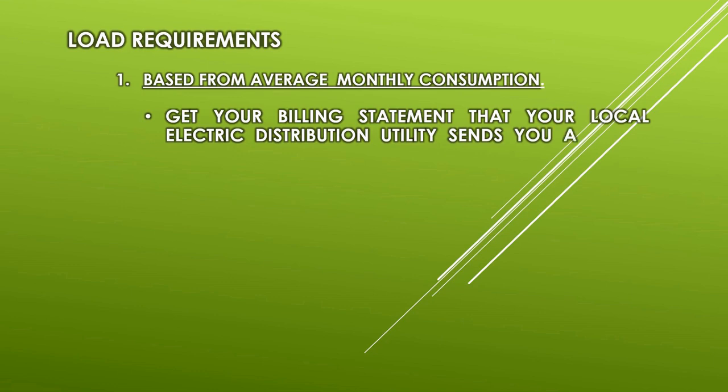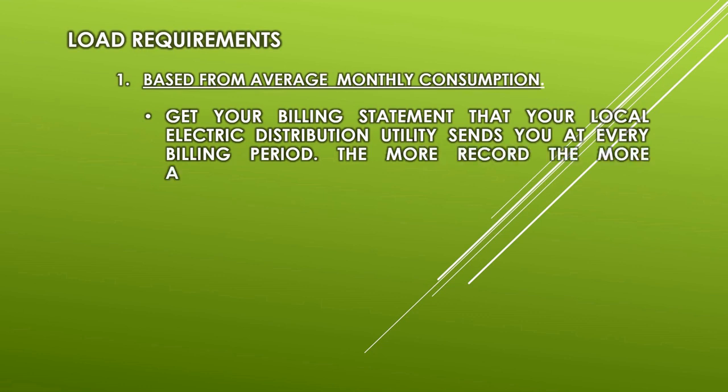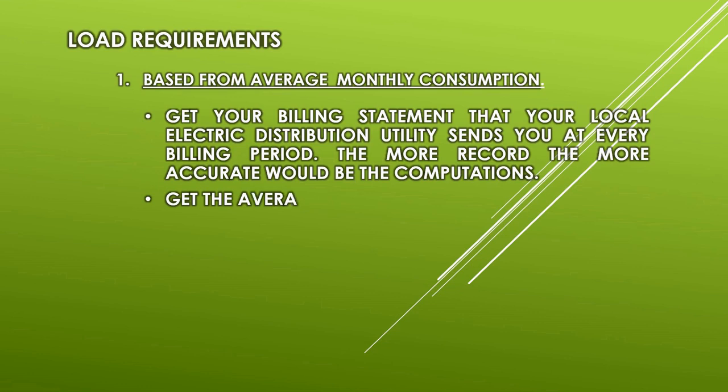Load requirements. Based from average monthly consumption. Get your billing statement that your local electric distribution utility sends you at every billing period. The more records, the more accurate the computations would be. Get the average monthly energy consumption.